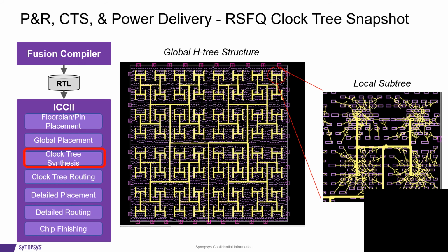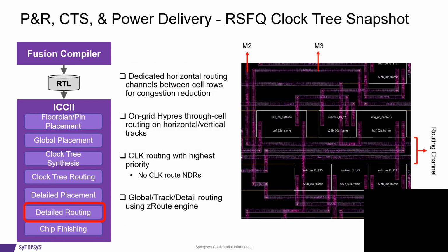So the splitters will make sure that each endpoint, similar to here that I am hovering over, are all equalized in the delay. And for each end, you have a few sync points locally that are also managed very nicely to equalize the delay of the clocks. That's extremely important. There are many methods of clocking. For this particular example, we use that clocking method, and I won't focus on other ones for the time being.